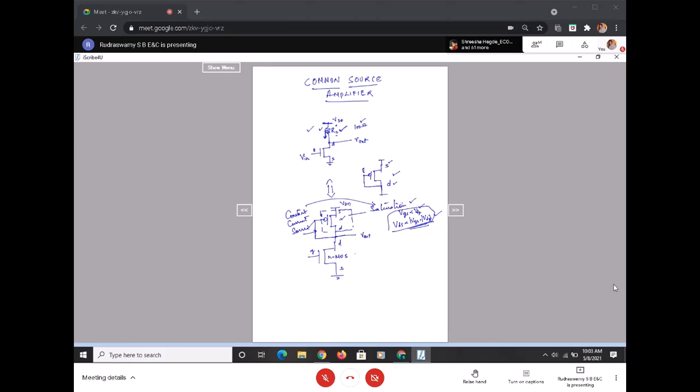Now I call the bottom one M1 and the top transistor M2. And M2 is basically a constant current source for me. And M1 is nothing but what? My common source amplification is all about it. So this is the NMOS transistor I use for common source amplification. Again, it's an NMOS. What is the gain of this particular NMOS transistor?